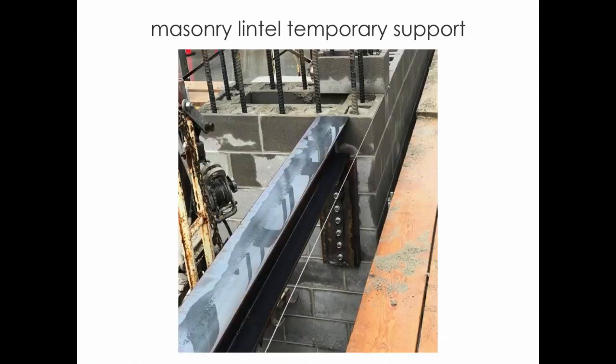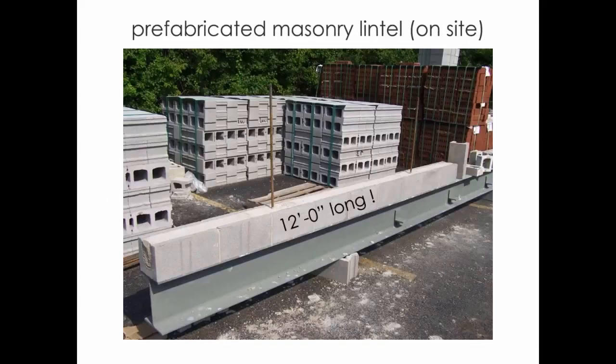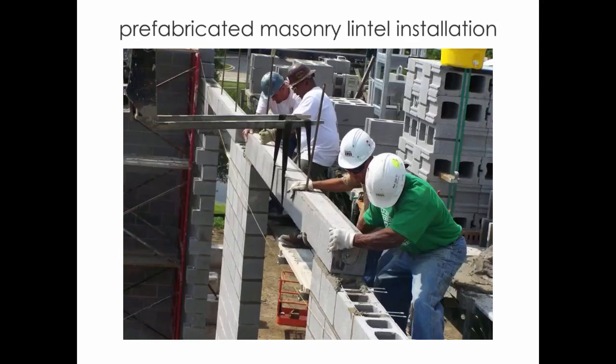This was actually a long span, a 26-foot long, where they got pretty elaborate with what is a temporary shoring for a masonry lintel. They didn't want to leave the steel in place because of all the other problems that it creates. Use a wide flange member just for shoring, and then they're going to pull that out later. Or a couple 2x4s. But like I said, prefabrication I think is something, this is a few years old, this project. You pick it up, lift it into place.